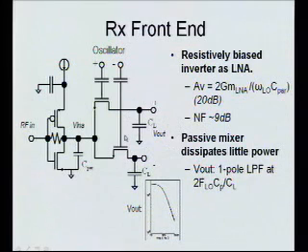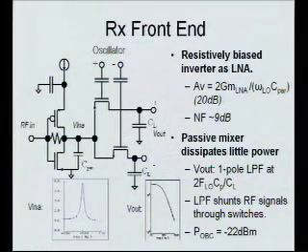And then it does something really cool, which is that it shows up on the input as well, because it keeps shorting the output to the input. And so you get what looks like a really high Q bandpass filter right there. And the cool thing about this is if you think about linearity, linearity is set by two things typically. It's set by the input linearity, so if I swing this input signal too much, I'll drive these things off.